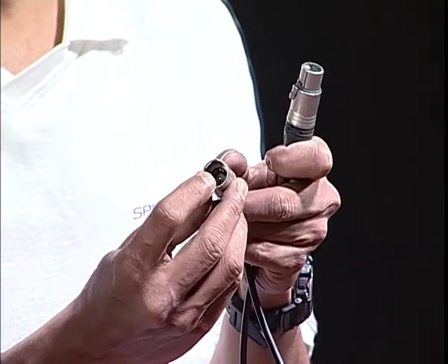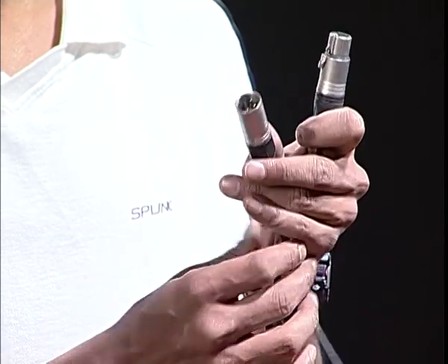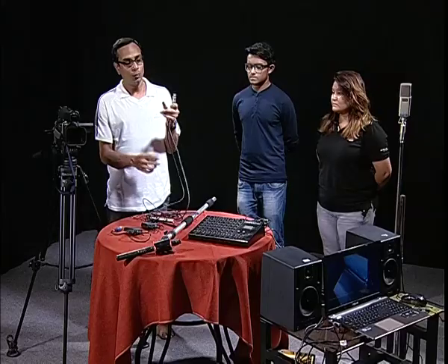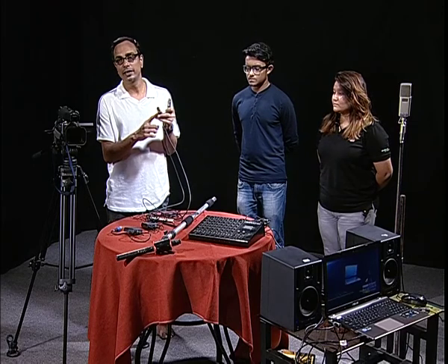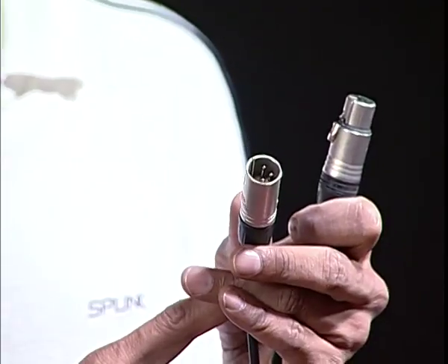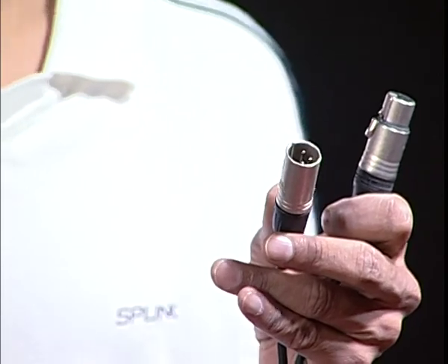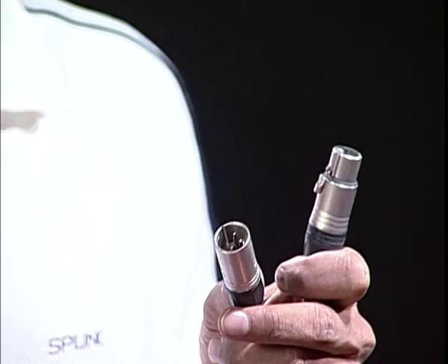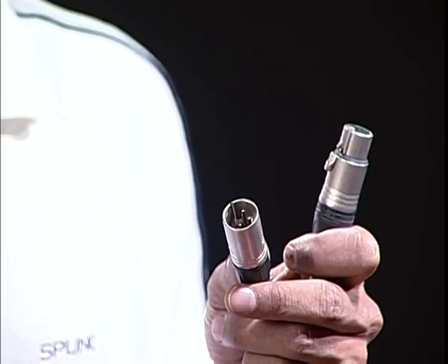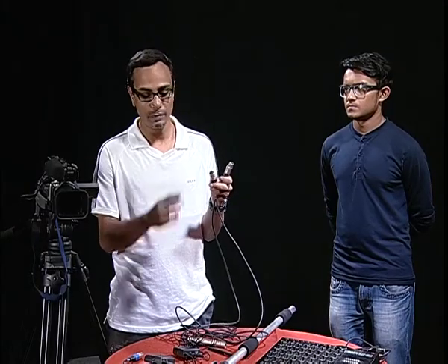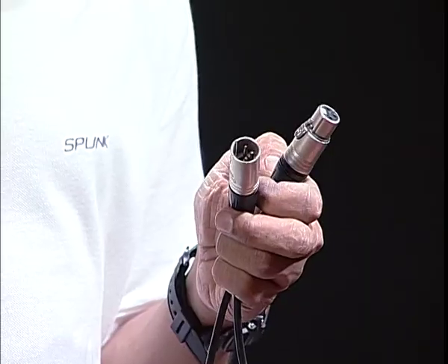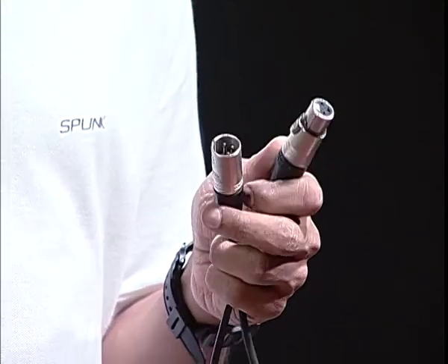You can make out that there are three wires running inside the connector. One wire is carrying the signal, so that's the positive wire. One wire is carrying the negative signal, and the third wire is basically grounding any noise which can be seeping inside this cable or inside the microphone. Noise can be generated from any high frequency source, for example noises generated from tube light chokes or from other electrical lines running along.